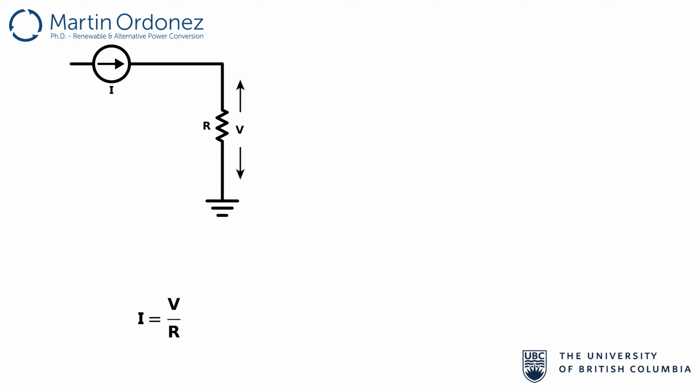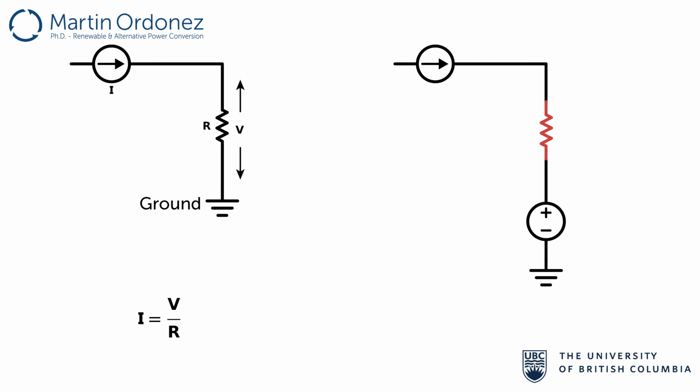In an electrical circuit, the reference point is the ground, which has zero voltage. Now let's compare the mentioned Fourier's law with this electrical circuit and equation. Since heat or power loss is related to the flow and displacement of molecules, it can be considered as loss current. Actually, the produced loss inside of a device leads to a temperature difference compared to a reference temperature. The reference point depends on the connection of the component.